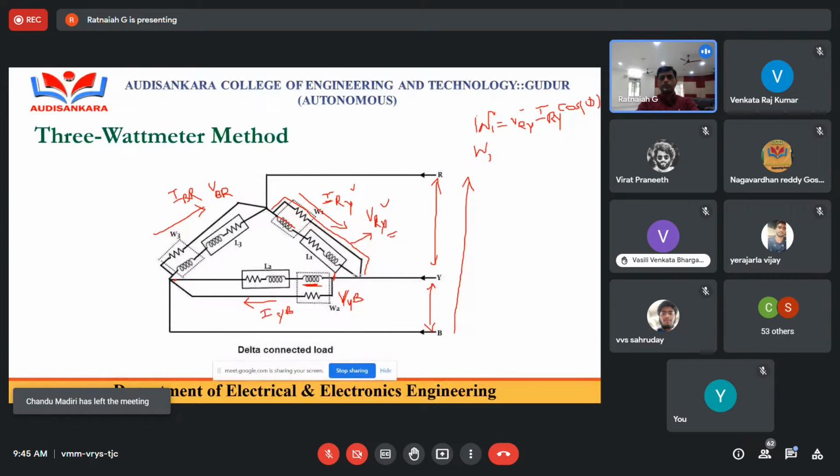That is W2. So W2 is this one. So what is the current IYB? What is the voltage VYB? Therefore, I can take this as VYB into IYB, that is the next phase current, into again cos phi. So that we are having the same. Because if the load is equal, then each phase angle is to be the same, that is phi is the same for each phase. Then coming to the next wattmeter, W3.